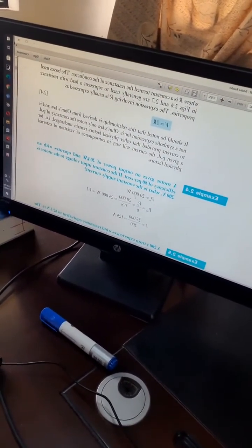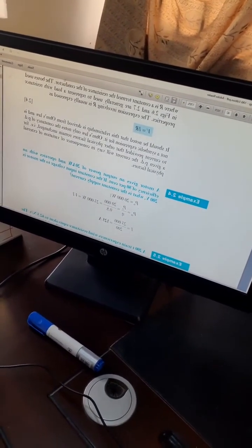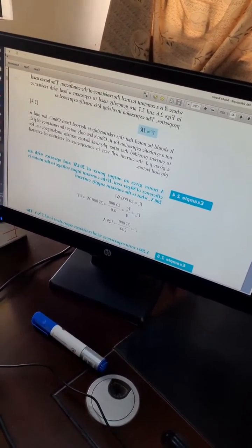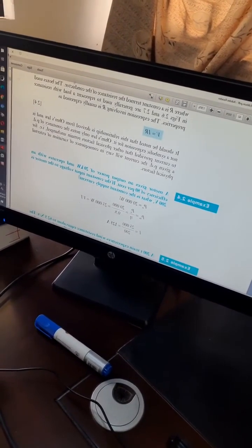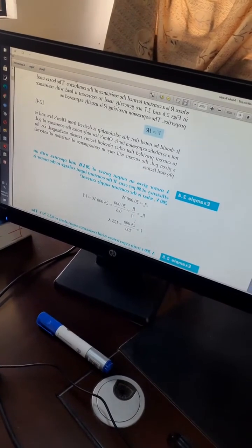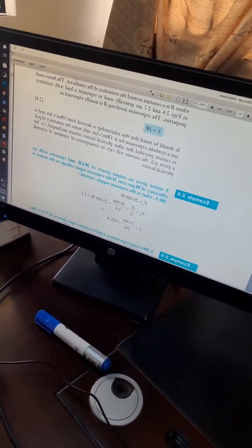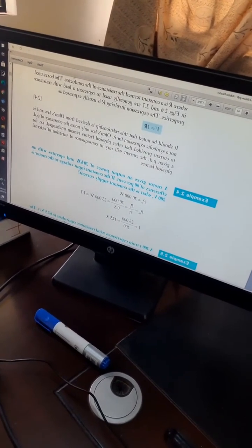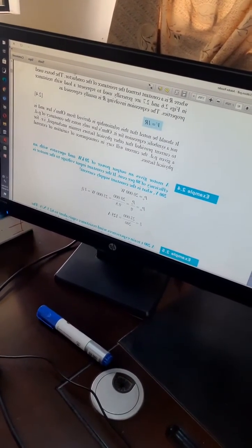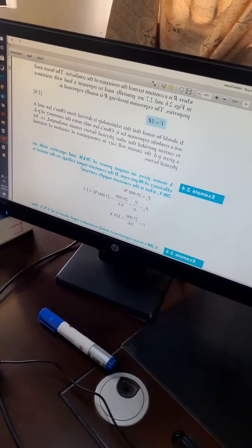The output power is 20 kilowatts. And then we have the efficiency, so we can know what power goes in. If the efficiency is 0.8, it means the input power is actually 25 kilowatts. And then set that equal to VI. They say the motor has 80% efficiency.